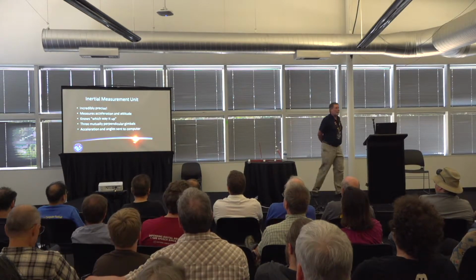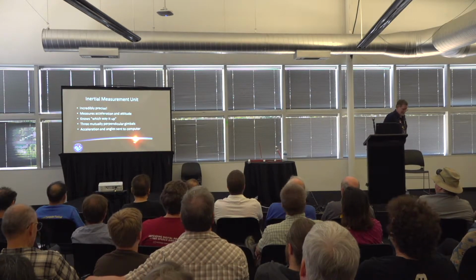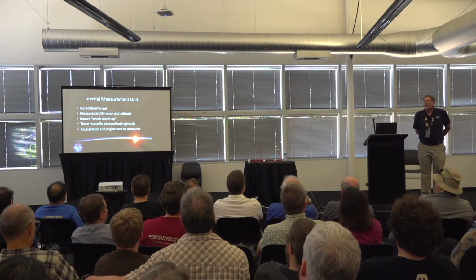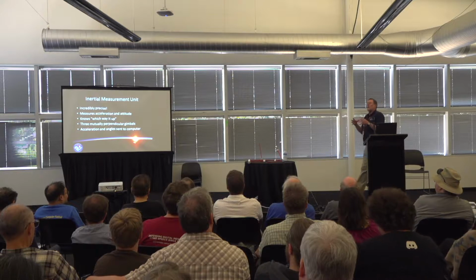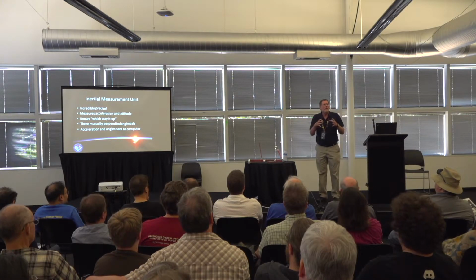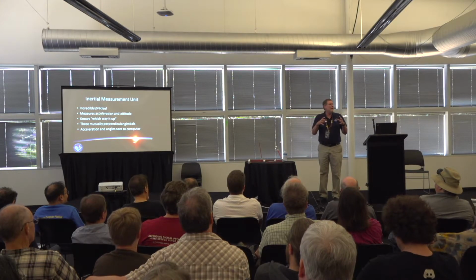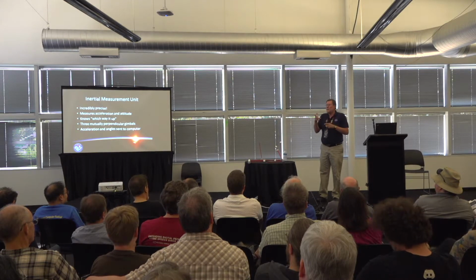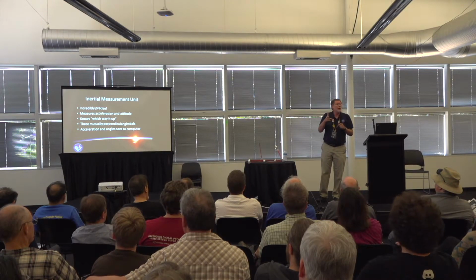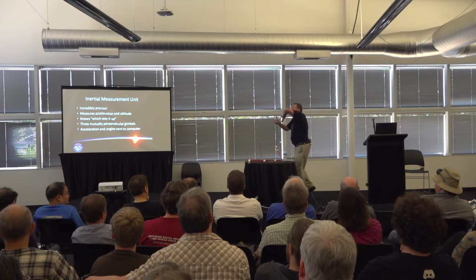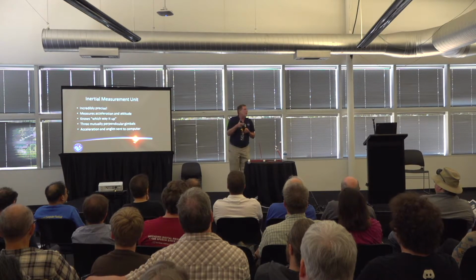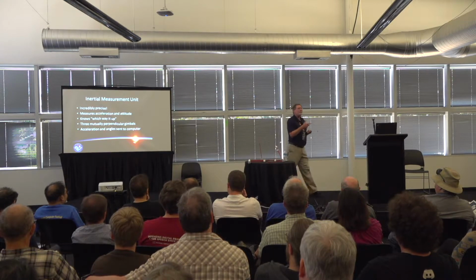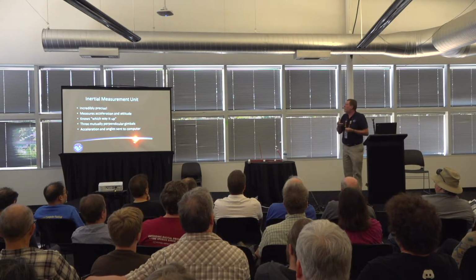We got to figure out which way is up. We have this inertial measurement unit. Michael talked about it. It's what we call a stable platform. It's about that big. It has mutually perpendicular gyroscopes. It holds it fixed in space. The spacecraft rotates around it. It's a beautiful piece of mechanical engineering, easily the most precise piece of equipment in all of Apollo.